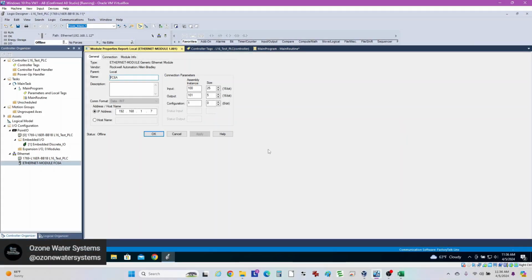Today's video, I'm going to demonstrate how to connect into our Ethernet IP bridge. It uses an IDEC bridge, and this will show you how to connect into it with your Studio 5000 with the CompactLogix or ControlLogix PLCs. We use this bridge to tie the Modbus signals from our Ozone generators through the bridge, and then to communicate with your control system with your Allen Bradley PLCs.